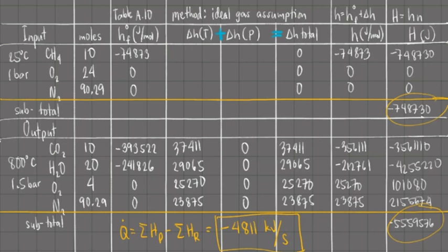Okay? And that is the general flow of solution for incorporating chemical reactions to our usual energy balance using the first law of thermodynamics. For an orderly solution, I would encourage you to follow the same format of the table whenever we are dealing with such problems. Okay? This format of the table allows us to specify the values both from the material balance in the form of the number of moles and the energy balance in the form of the enthalpy departures.